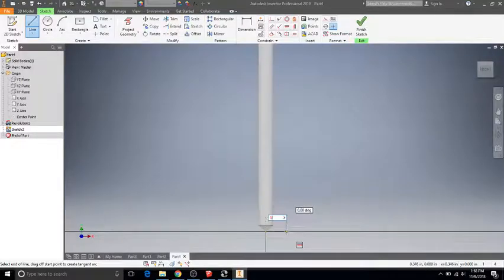Horizontal 0.125. Enter. So we got that. This sets the radius of the coil, how it's going to be winding. The first line. The next line I'm going to draw sets the axis of what it's winding around, and I'm going to go all the way to the top, even though our winding pattern is not going to go all the way to the top.